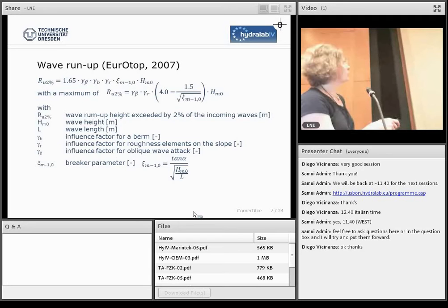What was our time schedule? We did the tests at the DHI in September and October 2012. We had 2 weeks for the general model setup, for instrumentation, for overtopping tests and calibration. Then we did our wave overtopping tests in 1.5 weeks. After that, we changed the instrumentation to prepare for the run-up tests, and had 1 week for all wave run-up tests.